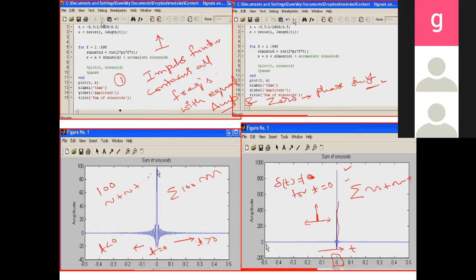And the second point is the signal to be analyzed may contain all possible frequencies with varying phases. So these are the two characteristics here. With the first one, since it contains all the frequencies with equal amplitude and zero phase shift, I can predict a system's response if I know the impulse response of a particular system, for any possible new input.